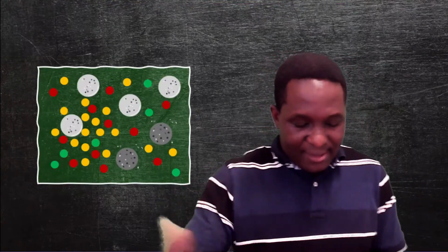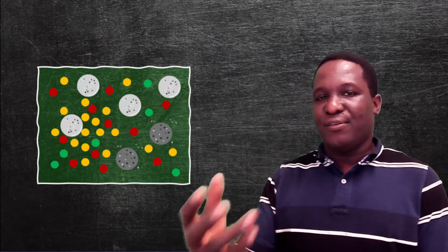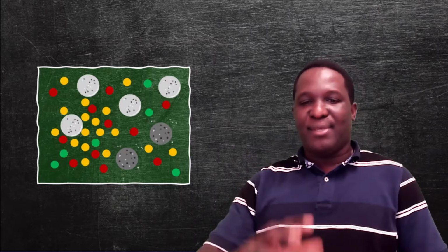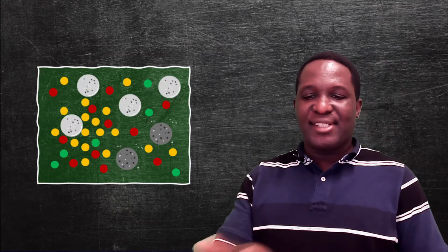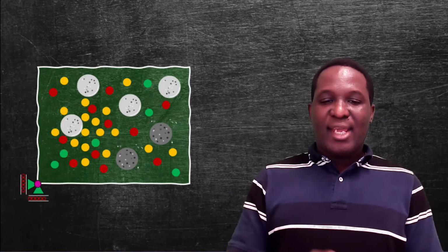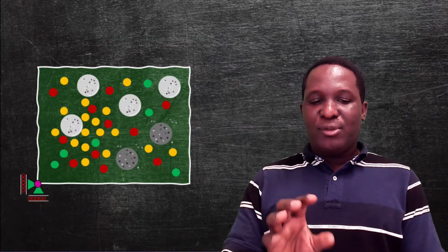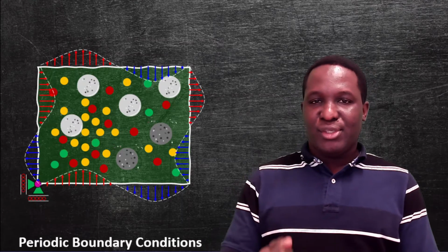So let's then begin to think about how to implement this numerically within the idea of this combined loading. So we start off with a representative volume element of this problem. So this is a typical UD composite, maybe with other asperities within it. And so what we're going to do with this case is we are going to hold one end, so apply one loading on one end, and also implement periodic boundary condition to this domain.